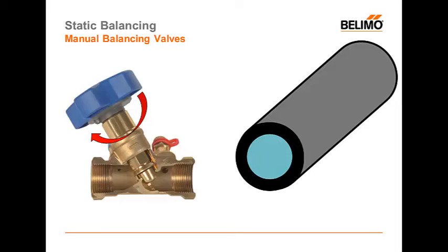In order to push water through a smaller area, we have to use energy, and in this case, the energy is water pressure. So pressure is lost as we push what should be 100% of water that in a fully open pipe through a restricted area, and this is what creates the pressure loss, which is the desired effect of a balancing valve, to consume some of the excess pressure in the loop.